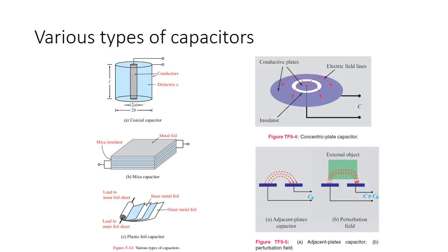Generally, we don't use these in consumer electronics, because if you're just trying to make a normal capacitor, there are cheaper ways to do it that take up less area. Your area here is going to be growing significantly larger, and you're not going to get nearly as much charge on those plates.